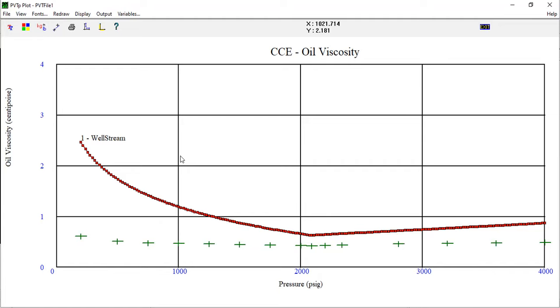This is because the GOR is path dependent, and thus using a different separator train would result in a different GOR being calculated. After pressing calculate, we wait until the simulation is completed. When the simulation is completed, we show the plot, and we can see that the current prediction and the data don't match. All right, so far so good.